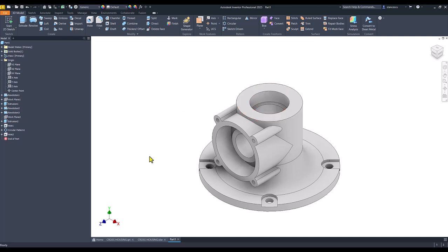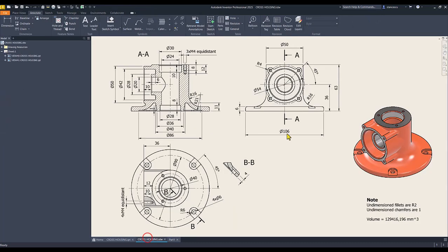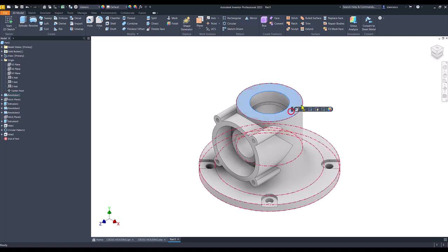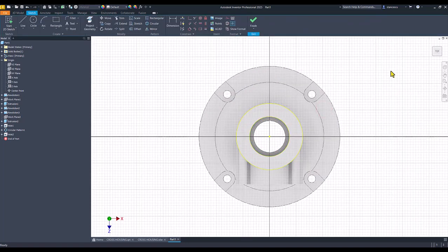Now the other one, which is placed to the right on a circle of 40. So I create a new sketch. I draw a vertical line with a length of 40 divided by 2.